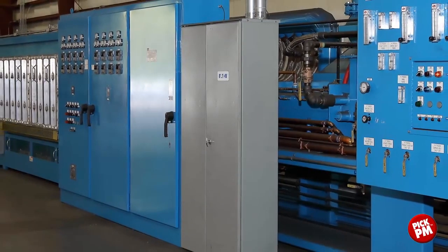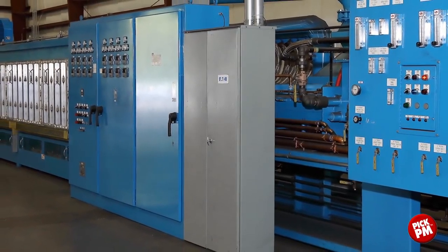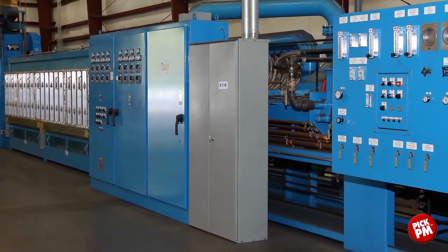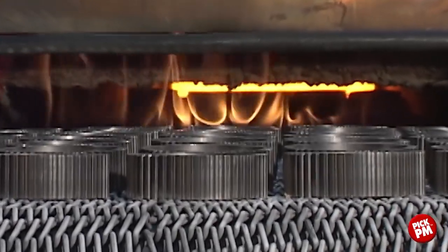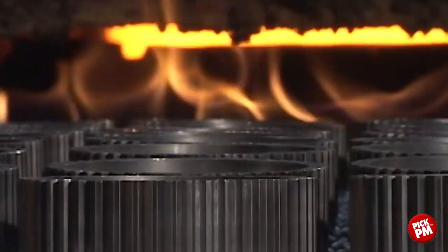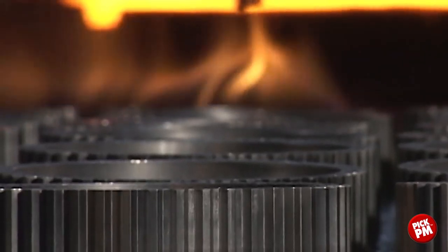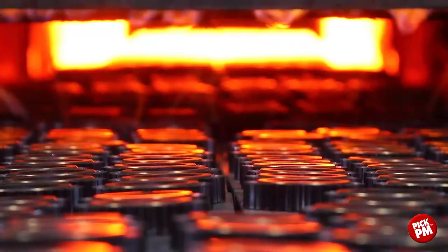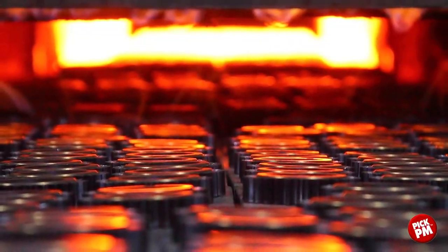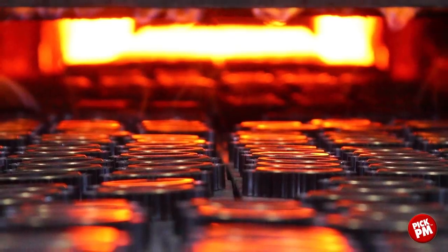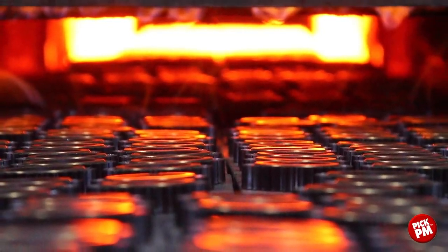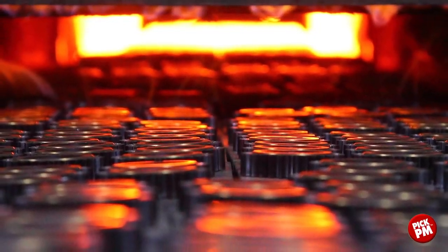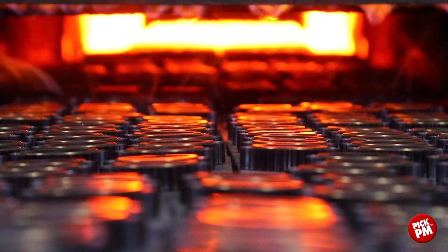So after parts are compacted, they're taken to the sintering process and put into the loading zone of the furnace. This is a continuous mesh belt sintering furnace, and the lubricant that was used to facilitate compaction will be removed in the delube zone at approximately 1350 degrees F in a protective atmosphere. After the delubing, the parts enter the high heat zone where they're sintered at 2050 to 2100 degrees F. Sintering is the formation of strong metallurgical bonds between the powder particles that have been consolidated in compaction.